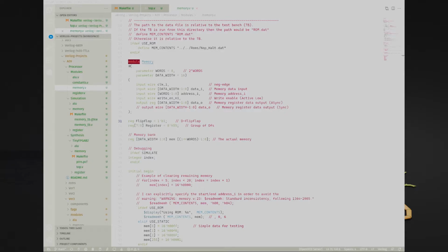The question is just what kind of memory was synthesized? Did we actually get single port RAM or something else? Perhaps we just consumed a boatload of registers, or maybe we utilized something more efficient like RAM. We should investigate what just transpired. So even though our Verilog code looks much like a bank of registers, the toolchain may infer it as something else entirely. We need to satisfy the pattern the toolchain is looking for.